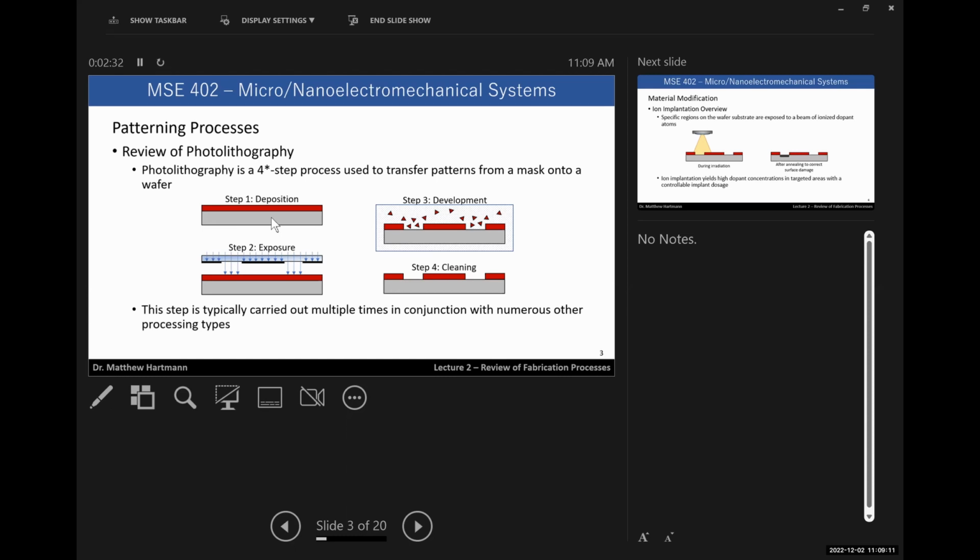There are literally thousands of different photoresists that are used. The ones that I have the most experience with are 1813, which is a pretty general polymer photoresist, and then SU8, which is an epoxy-based photoresist that makes more permanent microstructures. You literally have to burn or ash off the SU8 to get rid of it, whereas 1813 can be removed just with good old acetone and isopropyl alcohol.